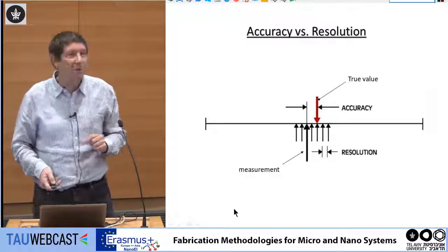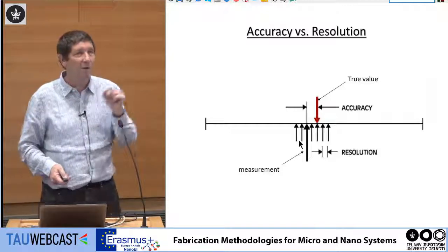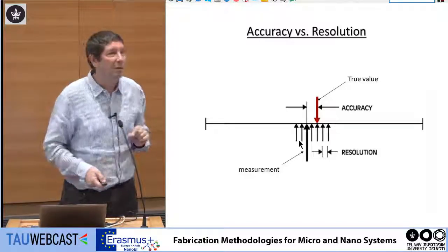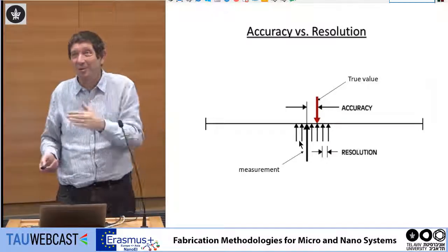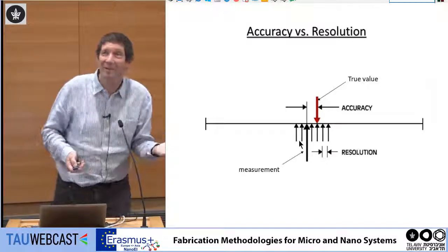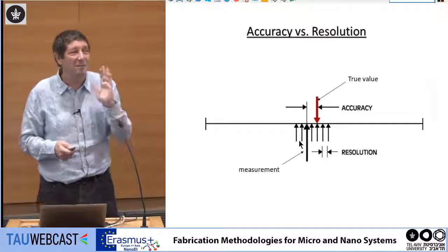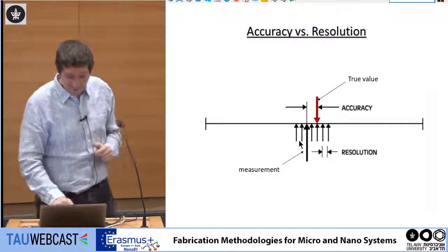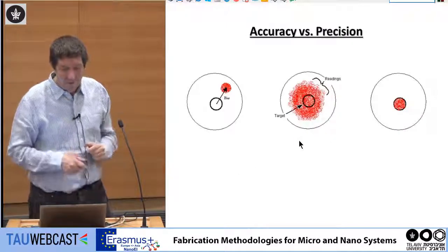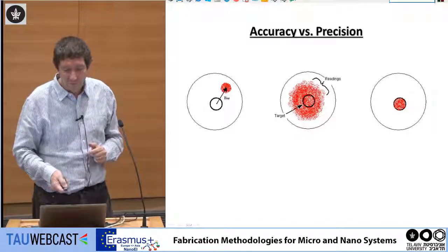So resolution is how small you can measure. Accuracy is how far you are from the real result. Now the question is, what is the real result? So we need to calibrate it, and ask how accurate the calibration itself is. There should always be a standard, some absolute measurement that we can trust. And it's not trivial.